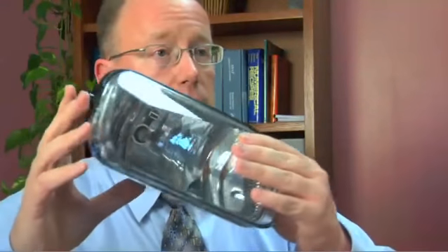Absent from most new cars are the traditional sealed beam parabolic reflectors and cylindrical cover lenses, simple examples of which we can see here. These are being replaced by segment reflectors containing clear windscreens, an example of which I have here. Segment reflectors transfer the optical power or beam-shaping refractive qualities of the cylindrical cover lenses to individually curved and oriented segments comprising the reflector.